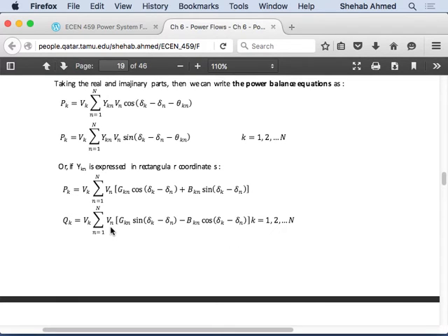So at a load bus, I can use these two equations at that specific bus. At a slack bus, I don't have anything unknown because I already have my voltage as a magnitude and an angle. So, and I know them specifically. So if I plug in here, I will know what's on the left-hand side without having to guess and estimate and iterate. That's a slack bus.